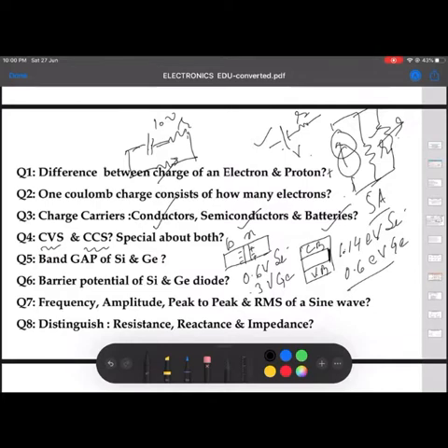You need two types of semiconductors in that, one N type and one P type. Whereas for the band gap, it is immaterial. It is simply a silicon semiconductor or a germanium semiconductor. Moreover, the units of this are of energy, that is electron volt, and the units of this are volts. I have very frequent interaction with students even at MSc level, and they get confused between these two terms which are entirely different.